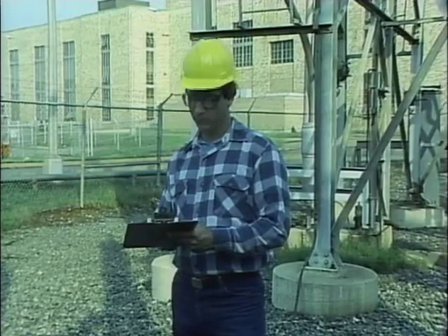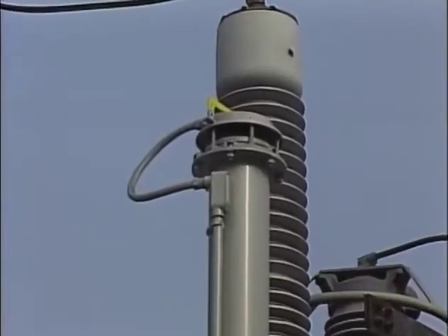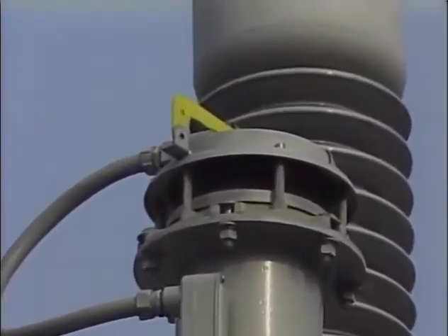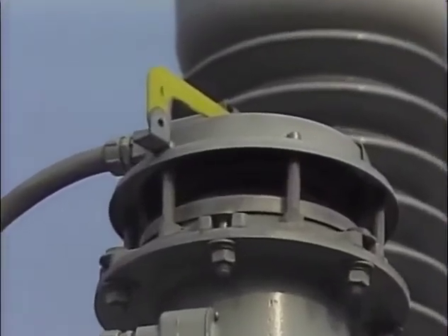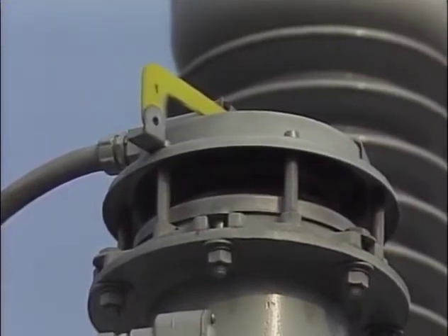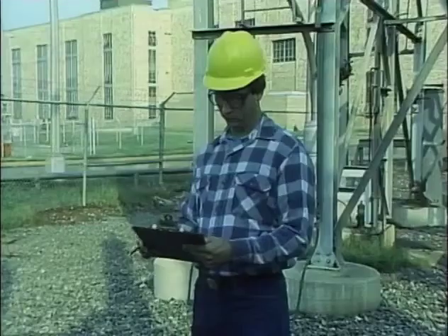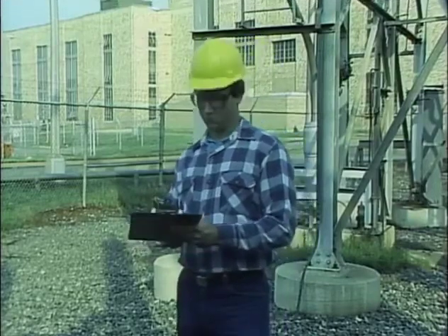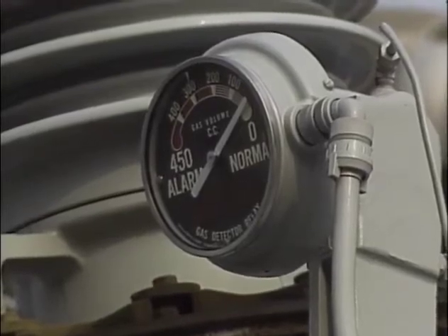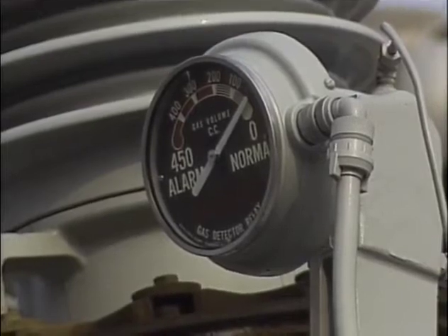Another indicator that is checked is the flag on a pressure relief device. If arcing occurs inside the reactor, gas is created that increases pressure inside the reactor. If the pressure increases enough, the relief device will vent the gas to atmosphere. When the device operates, a flag will pop up. A raised flag on the relief device should be noted so that if there is a problem with pressure, it can be corrected. An oil-insulated reactor may also have a gas detector relay. The relay measures gas in the reactor and triggers an alarm when the gas volume reaches a predetermined value. Gas volume is noted during the inspection.